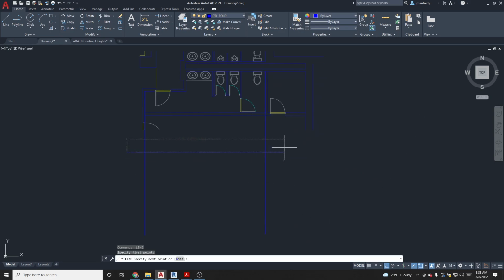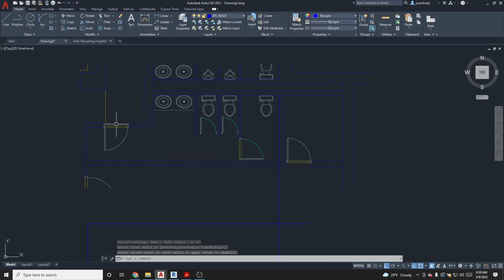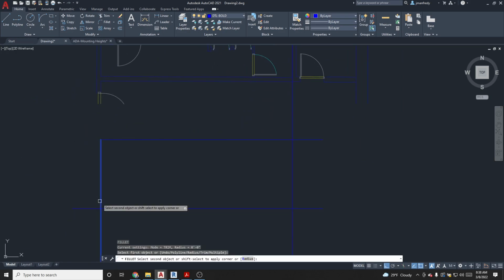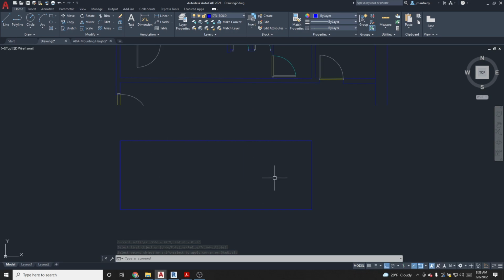Draw a line across the top for the ceiling, and I know this room has a 9-foot ceiling, so I offset, or O, 9 feet, and I fill it to create a rectangle. So these lines here are mimicking the size of the room. They're intended to show me this rectangle. I'm looking straight ahead at this wall, and that's an elevation there. Detail bold is a heavy line weight, so this line will appear thick when printed as a PDF.